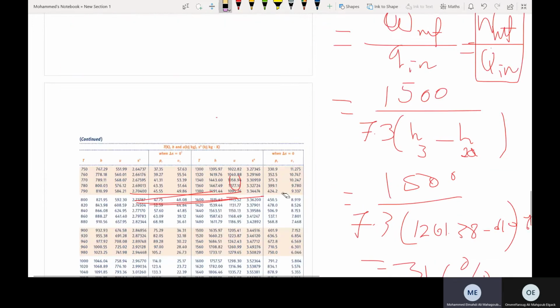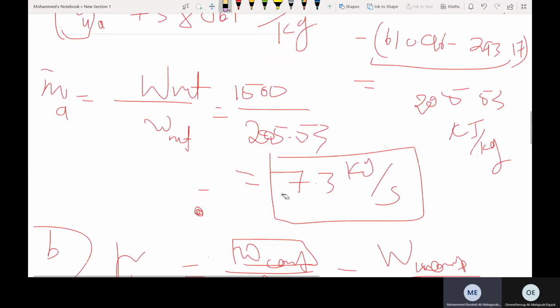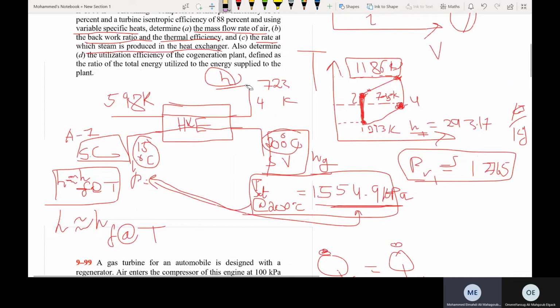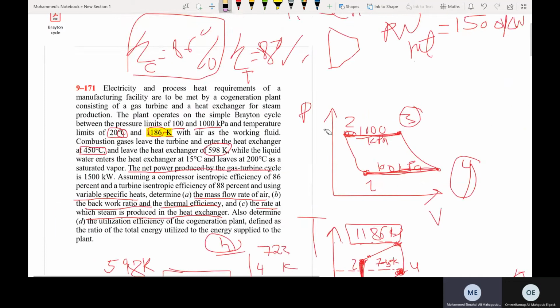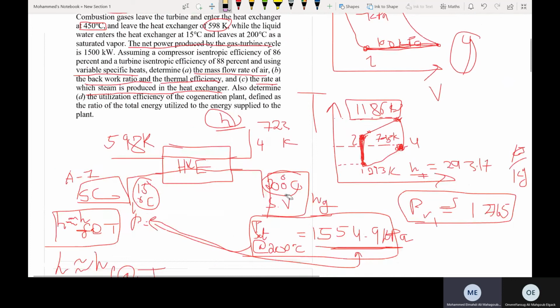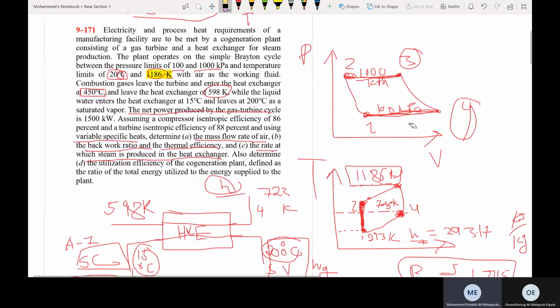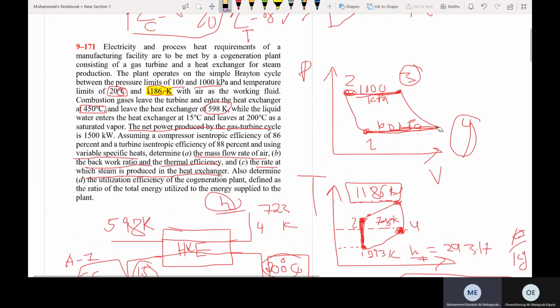And yeah, so that's it. There is a problem in the slides where this thing happens, I guess, but not with the Brayton cycle. I think with the Rankine cycle, chapter 10, but it's the same principle. Sometimes we can use the exhaust of the last point in the cycle and put it here with a heat exchanger, because the temperature of this point is not going to drop there like this.